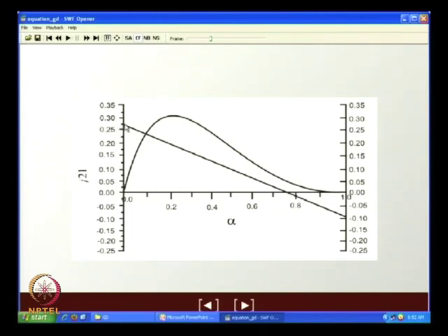We observe that suppose we increase J1, that means we increase the liquid flow rate, and keep J2 constant. What happens? The curve will be intersecting at lower and lower points. From a fixed J2, naturally the point of intersection will slightly shift towards lower and lower alpha. Quite expected. Higher liquid velocities, naturally in that case we will have a lower alpha.